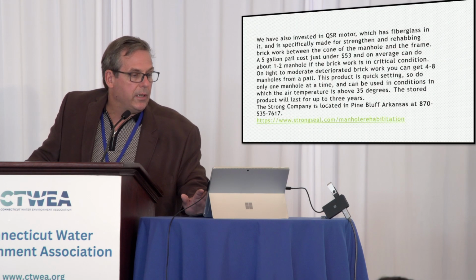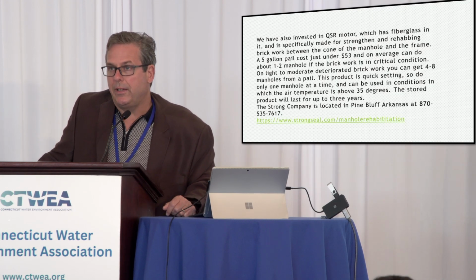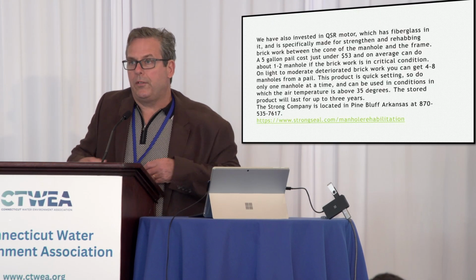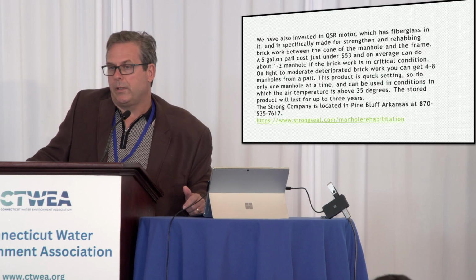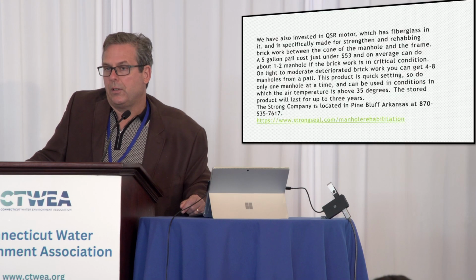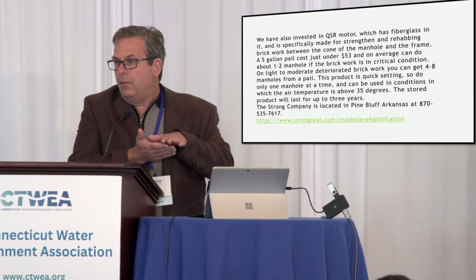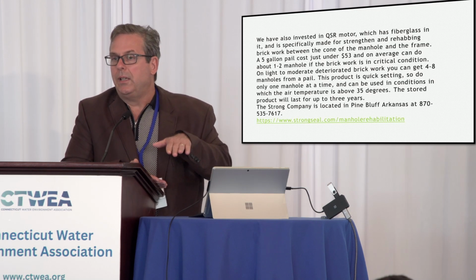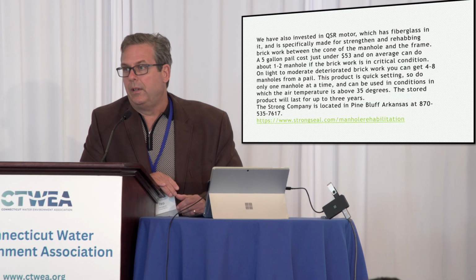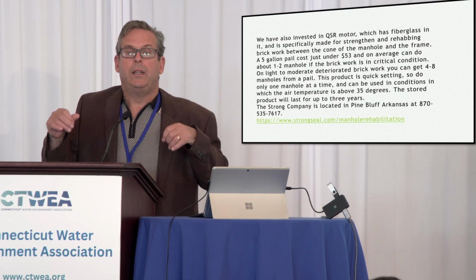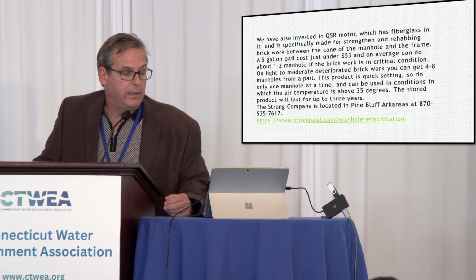And then the next thing I want to talk about is we worked with Green Mountain. Everyone remembers Ray Barr. He's retired now. But we did some work over the last few years with Green Mountain, and they used this proprietary mortar. It's called QSR. It's from a company out in Pine Bluff, Arkansas. This quick setting mortar is specifically designed for that space between the top of the cone and the frame. Usually if you have older manholes, there's going to be brickwork there. So when surface water gets into that area, it erodes the mortar, it starts to break up, the bricks get loose, sometimes they fall into the manhole.